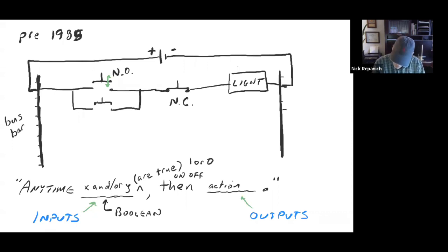In fact, if you remember, you probably had those little rocker switches that I gave you, and they had a couple little tabs. I don't know if we got this far, but you can buy a little rocker switch. Inside, this one is open, and this one is closed. So you can wire up to either the normally open side or the normally closed side. It's two switches in one, right? Not all switches have this capability of having either or, but that's when you had these three terminals. It was just two switches in one.